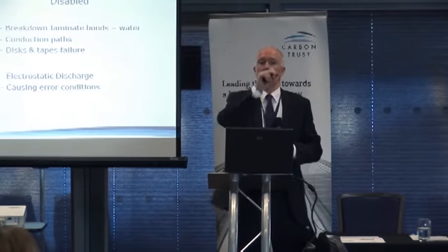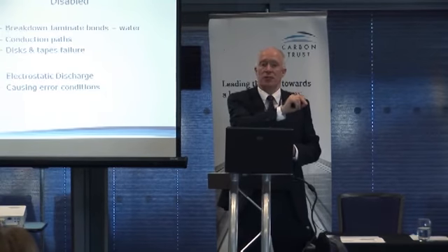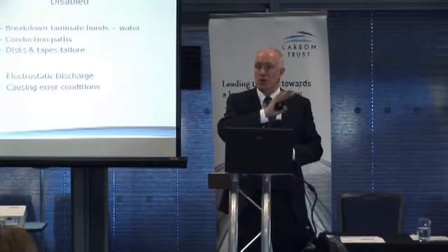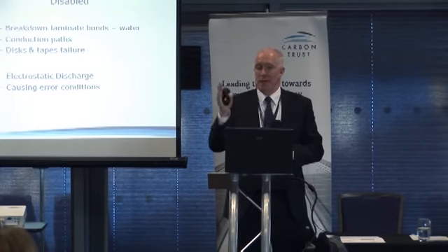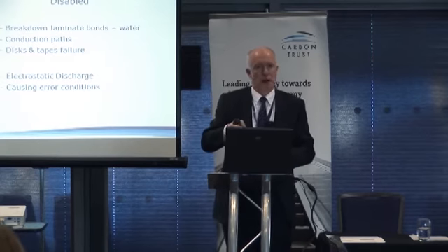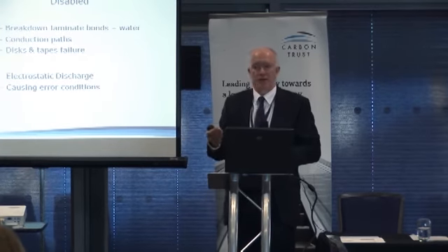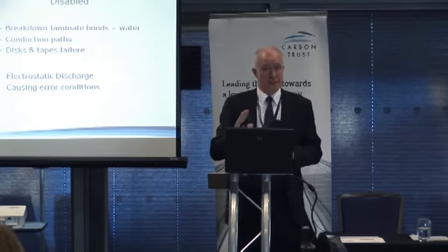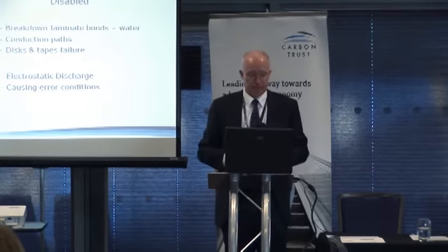Despite the fact that that will cause it to be 30 degrees centigrade or above at the back of the equipment, it is of no relevance to that equipment. It's the air on temperature. But often they get confused. They turn the temperature up, they say, gosh, it's really hot over here, it's 30 degrees centigrade, we've got a problem. They haven't. That's the outlet temperature.